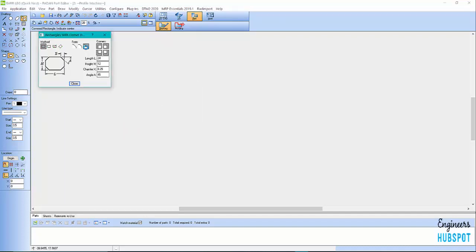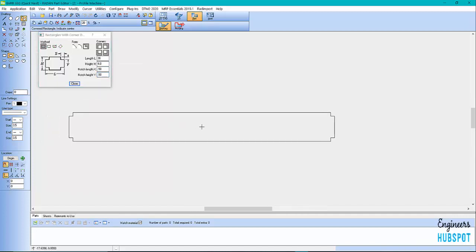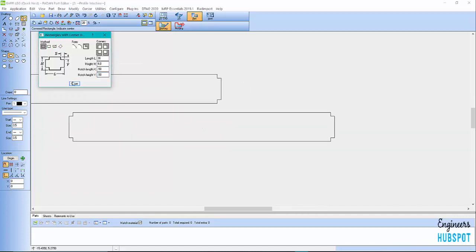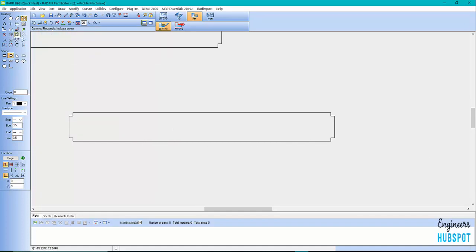So here you can see I've got some notches in all 4 corners. I'm actually going to do a rectangular notch, and I'm going to make this 36 long, and we'll skip down here and we'll go 4, right, and then our notches will be 0.5, 0.5. So there's my sketch, right?